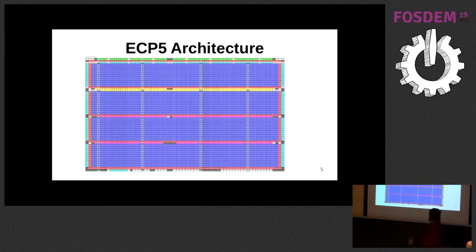So obviously this is not much use, but you can start to see some rows of RAM, lots and lots of logic tiles, and I/O around the edges. If you look at all these different things, you've got the yellow, which is DSP, and I/O at the edges, and finally the high-speed SerDes at the bottom.